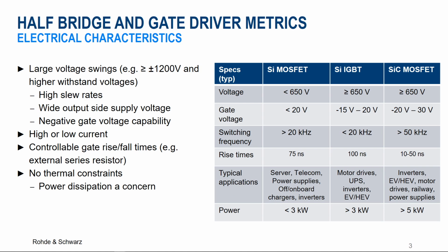Power applications will deploy different devices such as silicon MOSFETs, IGBTs, and silicon carbide MOSFETs depending on the requirements for power levels, drive methods, and operating modes. IGBTs carry a large amount of current with a low saturation voltage resulting in low conduction losses. MOSFETs also have low conduction losses, which vary based on their drain to source on resistance, or RDS(on). Because IGBTs carry higher current, they are used in higher power applications, while MOSFETs are used in high frequency applications where high efficiency is really the key.